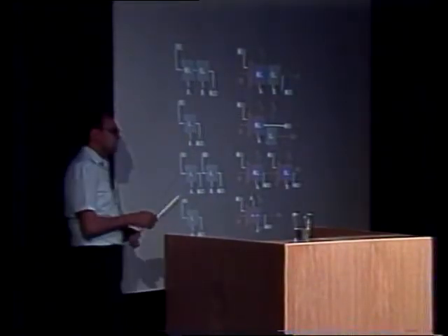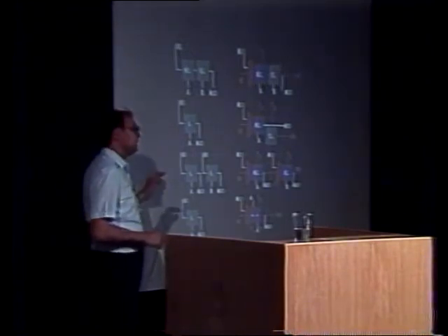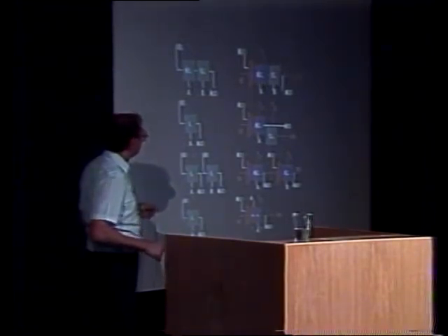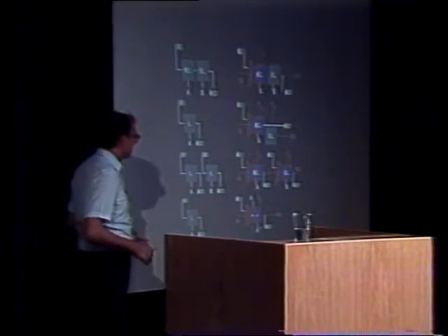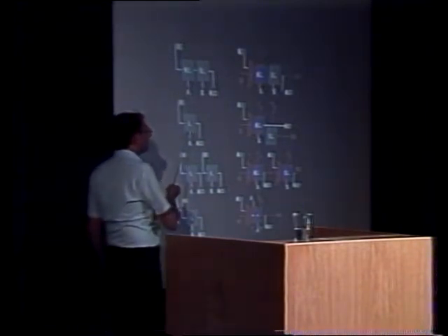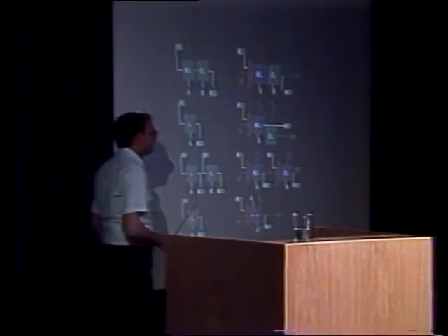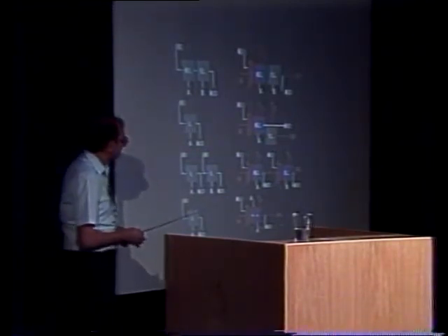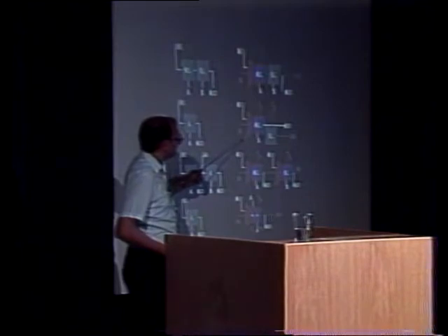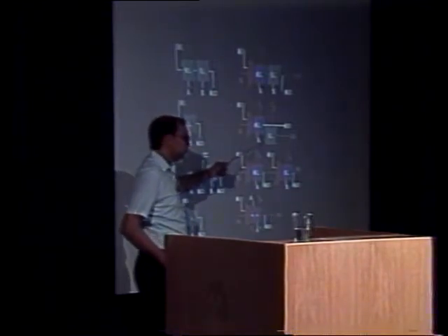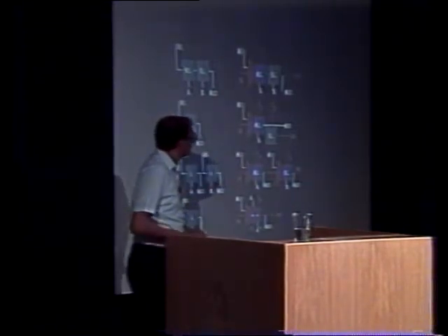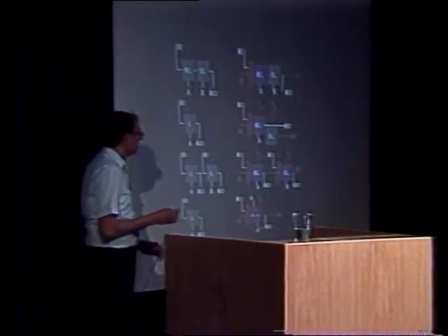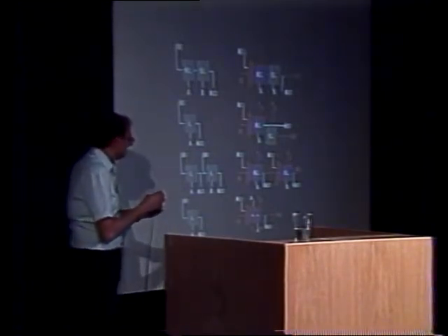But most of the designs in DEC, especially in the Hudson environment, are only single latch designs. That is, we have only latches surrounding the combinational network. Now here, if you want to implement the scan design, you not only have to add the mux, but you must add a whole slave latch. That's a lot of hardware, and no wonder designers don't like it.